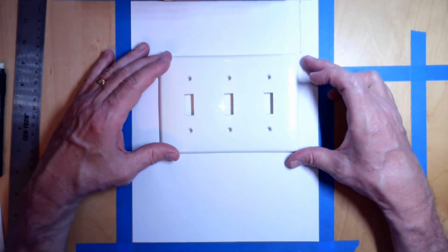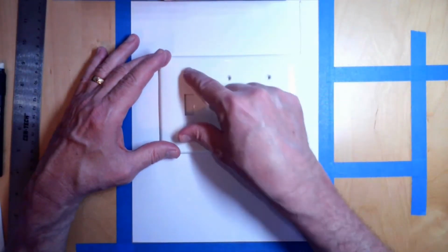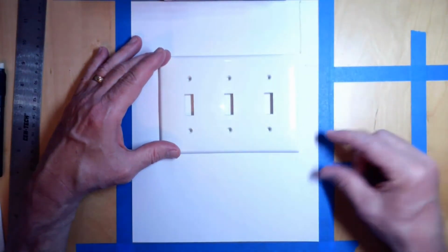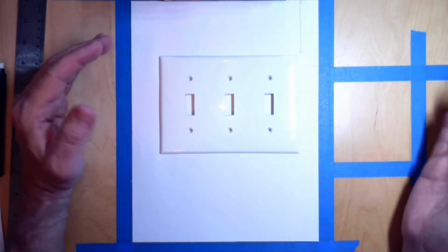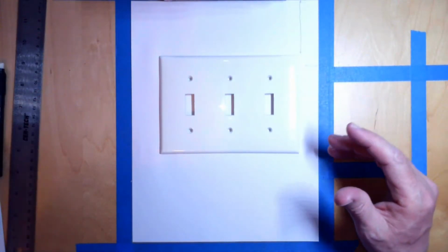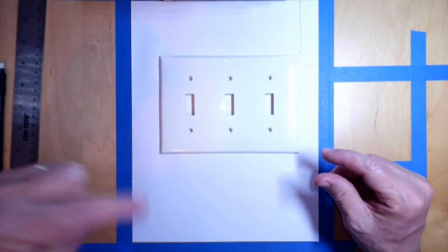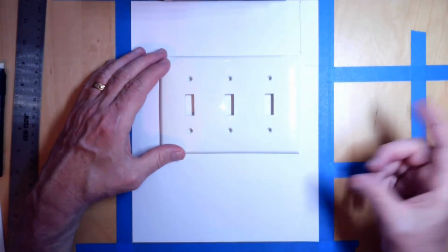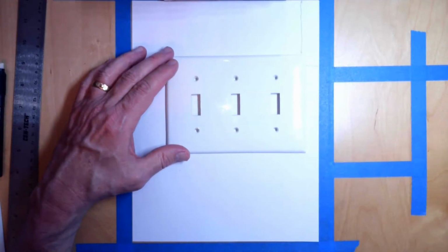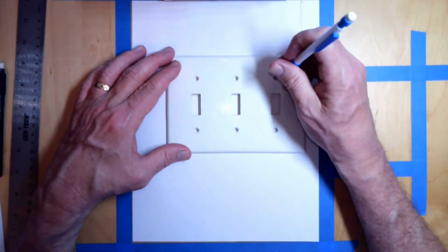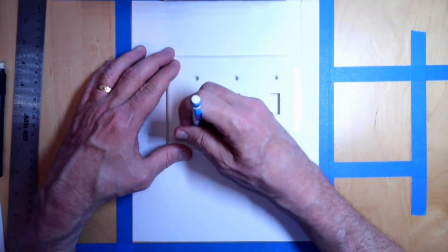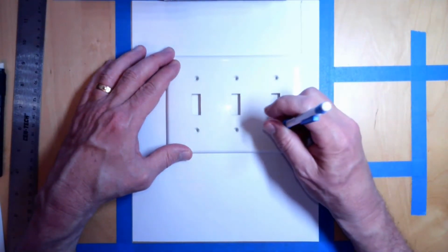So we have a larger tolerance zone for the pattern relative to, in this case, the edges of the wall. That right there is why we have our pattern locating tolerance zone and our feature locating tolerance zone with different tolerances. So the feature locating tolerance zone is the tolerance zone for these holes, and I'll mark it right here.